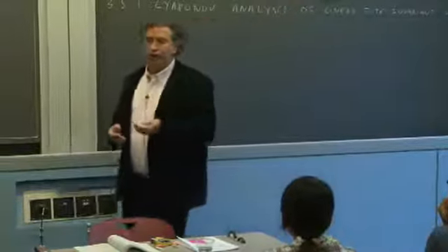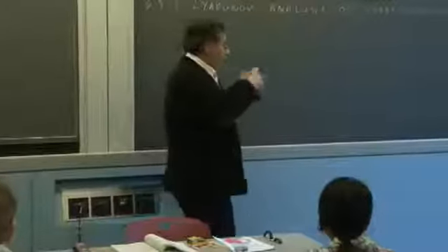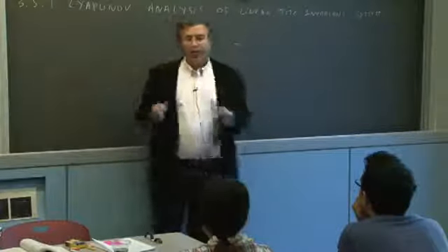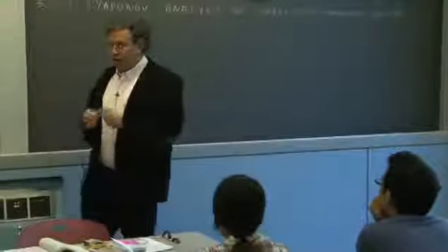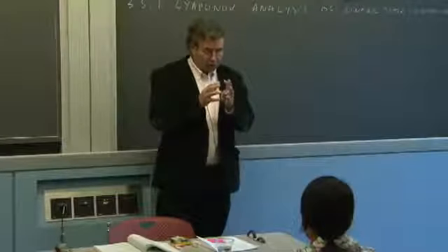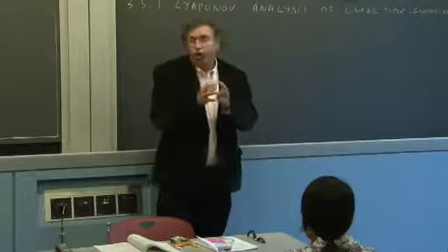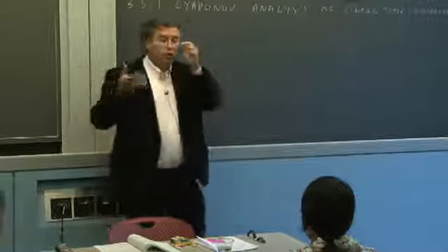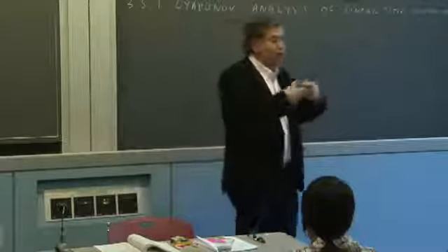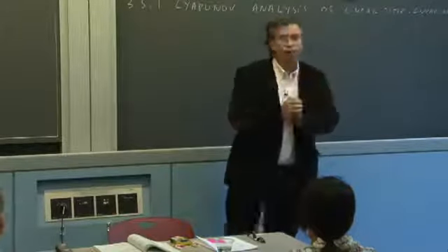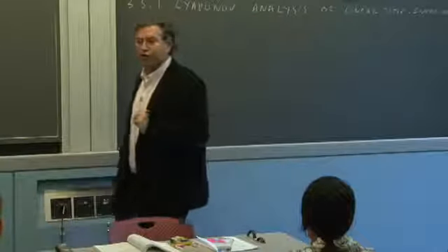But more practically, because Lyapunov functions, like energy functions, are going to add as you pile up subsystems, it's nice that if you have parts of your system which are linear, whether in the controller or in the system dynamics itself, they come up automatically with their Lyapunov function block. So that's why we were interested in deriving Lyapunov functions for linear systems.